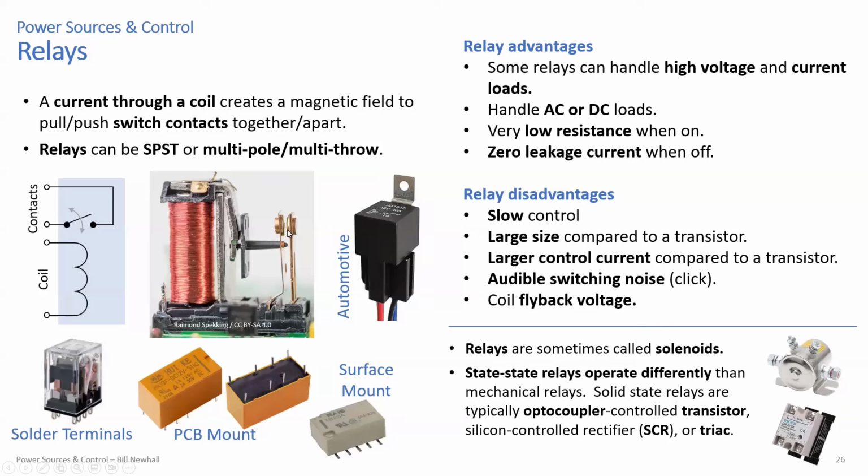as transitions happen. And they might be milliseconds apart, but you can get what are called bounces, which means that the switch looks like it's opening and closing a few times, or the resistance is changing of those contacts mating as the switch closes or opens. That's called a bounce. And if that's connected to a digital circuit that's, say, counting edges, then you can get multiple counts registered when the switch bounces.